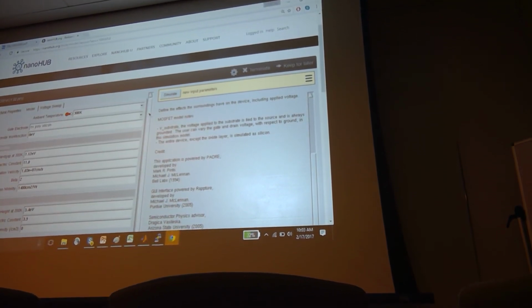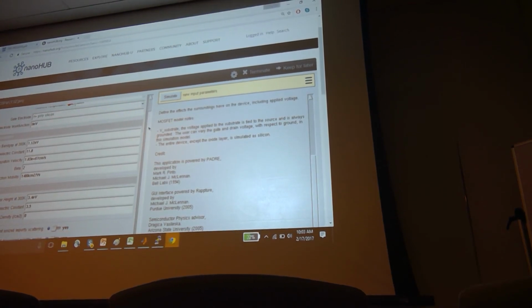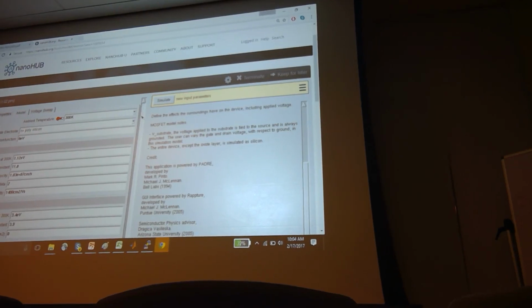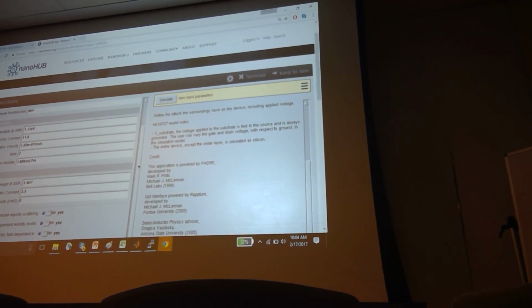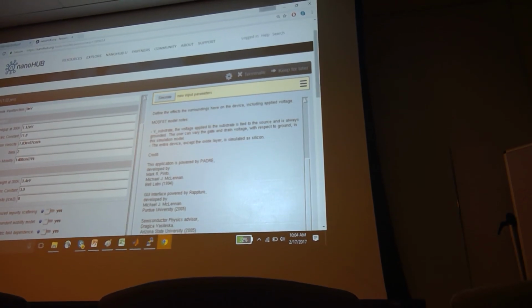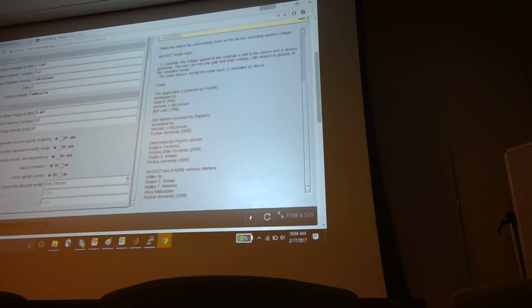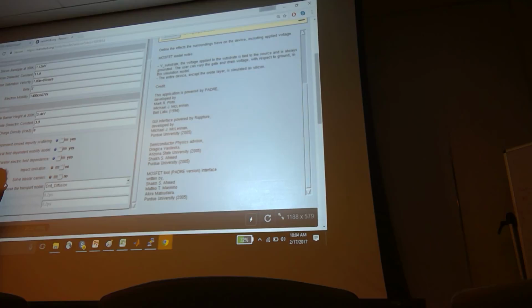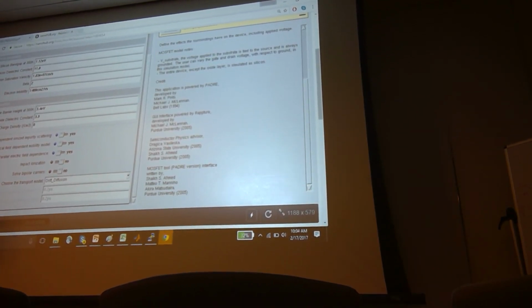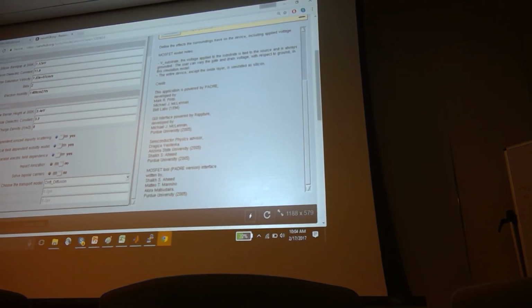Okay, model. Don't change anything here, okay? Everything is set to default, correct values. Set temperature is 300 Kelvin. For models, choose drift diffusion model. Now I know 45 nanometer technology has some ballistic transport in it, but forget that for now. Just assume it's a drift diffusion model.